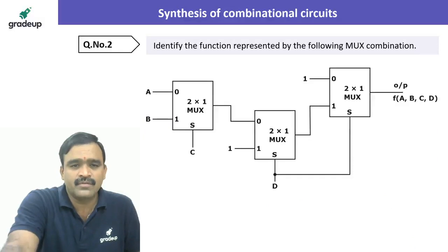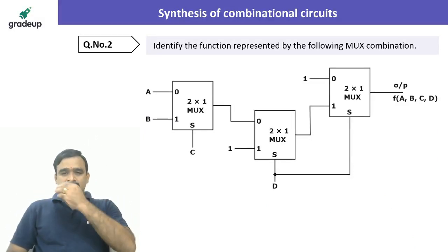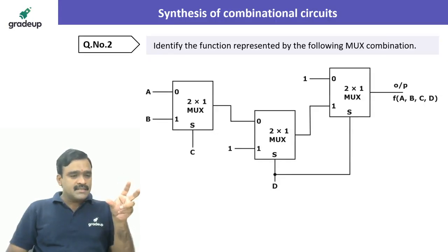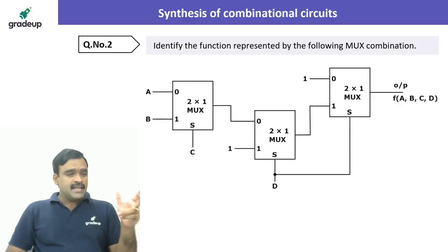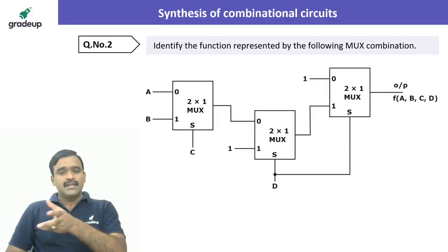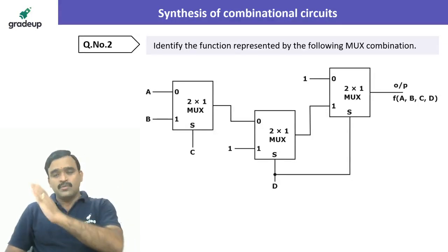Okay. Now let us go for the next question. It is a little bit more analysis, synthesis. What do you mean by synthesis? Actually, we have a syllabus like design and synthesis of combinational circuit and sequential circuit. Design is based on the requirement. We have to take the truth tables, the requirements will be taken, and accordingly the logic diagram will be constructed. Synthesis means we have to analyze the logic circuit for certain inputs, what output you are getting.